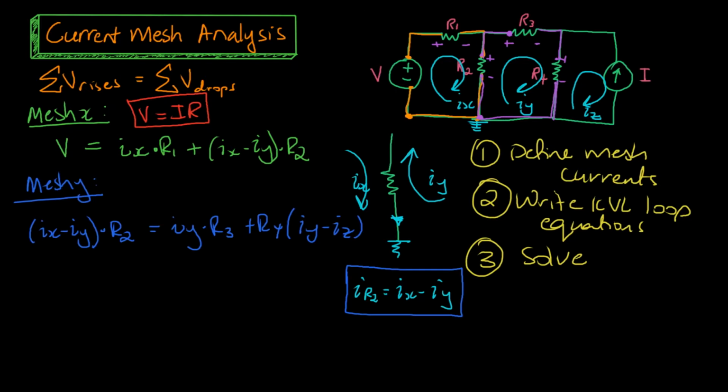the circuit. So if we trace around from our battery source here, we know the current's going to be pushed away from our positive terminal, up through resistor 1, and then it's going to want to come down to our reference node, which is our point of least potential. Some is then going to branch off into R3 and then want to come down here. And we know our current source is going to drive current around here. As resistors are always voltage drops, we need to define the positive terminal as where the current is entering.